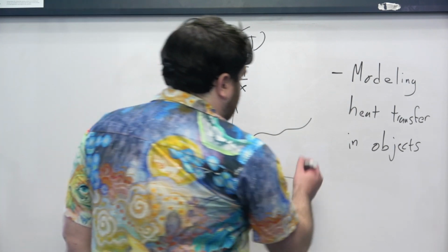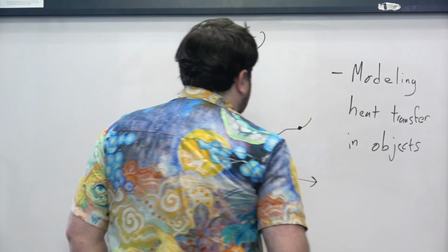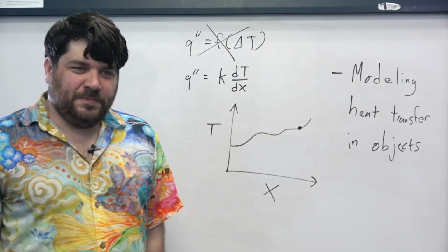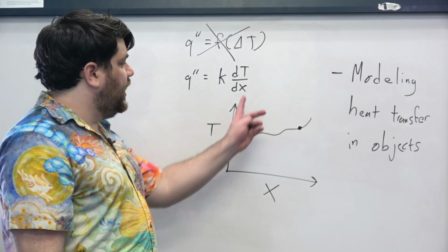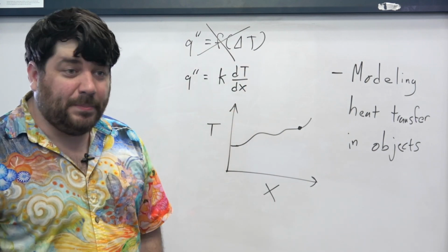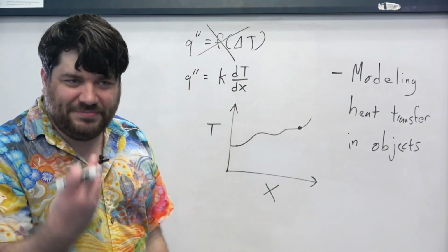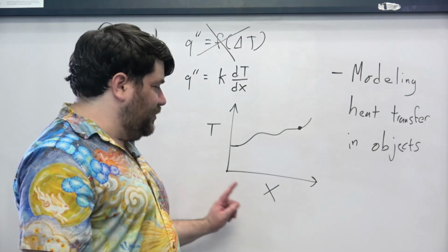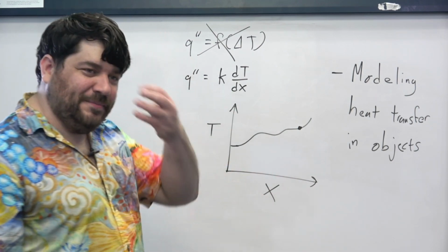And if I wanted to analyze the heat transfer, say over here, well, I have to analyze what the value of this dT/dx is. But because I've defined a specific value of x, it matters whether or not we define the x to go up this way or this way.